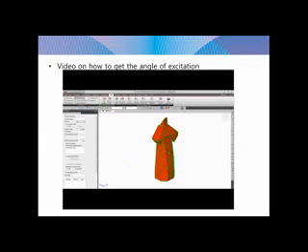So we have to run the analysis. So go to analysis and then press perform analysis. After running the analysis, go again to the dynamic load to know the angle of excitation. We have the earthquake major, as you can see it is 66 degrees, and the ortho is 156 degrees. Getting that, you can use Excel or any computation.